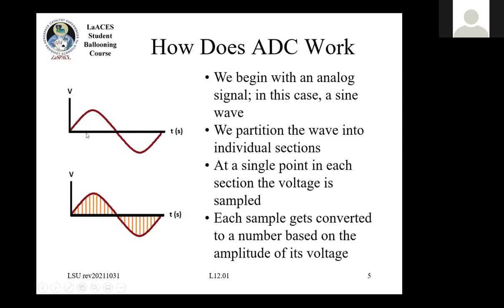your sine wave here, right? So if I'm sampling this sine wave at the same frequency, well, I'm basically sampling this wave in the same spot every single time, right? So let's just say, for example, I happen to match up on the peak here.